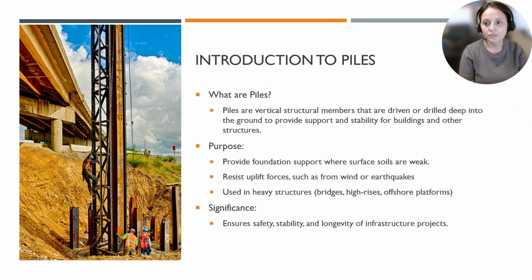So what are piles? Simply put, they're deep foundation elements. Instead of relying on shallow soils, which can be weak or compressible, piles transfer loads down to stronger soil layers or rock. They're designed to resist not just vertical loads, but also lateral forces and uplift, like those caused by wind or earthquakes. That's why you'll often find them under bridges, high rise towers, and offshore platforms. Without piles, much of our heavy infrastructure wouldn't stand.